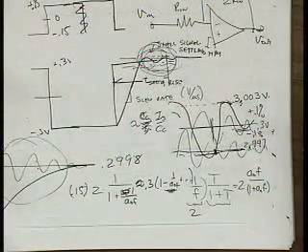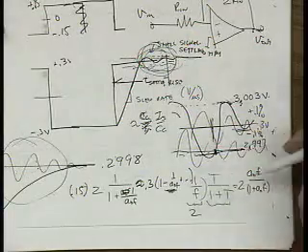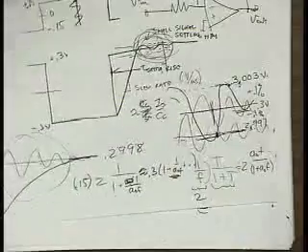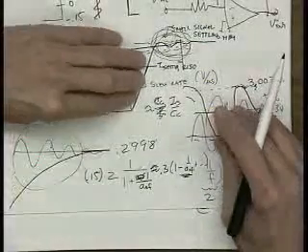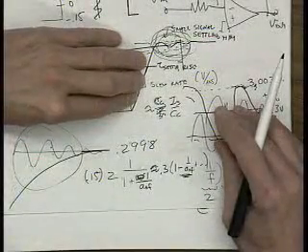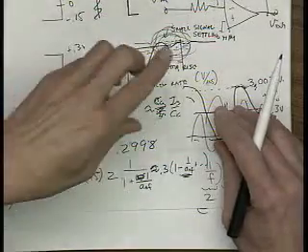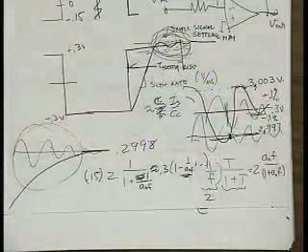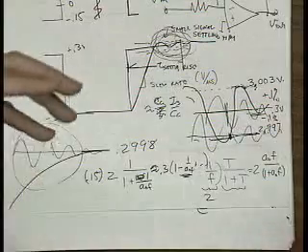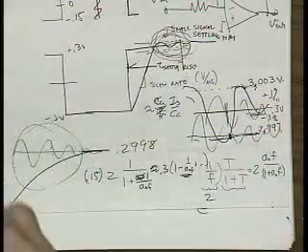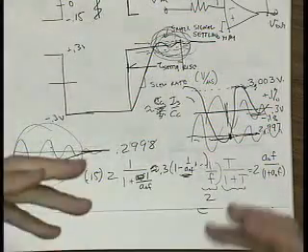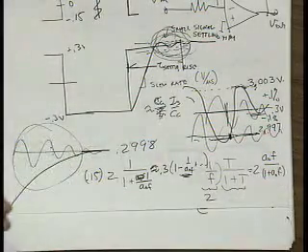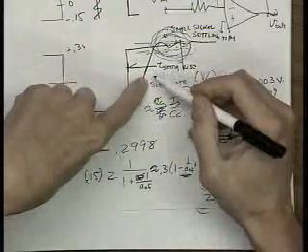It's not a direct relationship, because once you have multiple poles, which you're going to have in your amplifier, the single pole analysis I did won't quite hold. But it's kind of the right tendency. So settling, slew rate, you know what that's due to? It's due to the current and the compensation capacitor. But remember, I did that little analysis and showed you how it relates to the stability problem. You're not quite free to change ISS or reduce C sub C, because you have to worry about that. That's set by some of the stability criteria. So you've got a little box there.